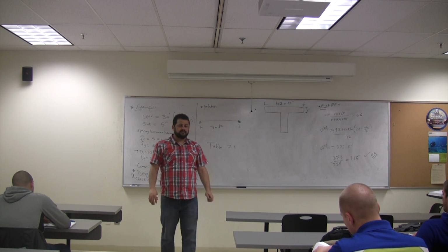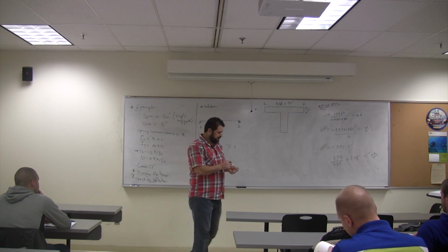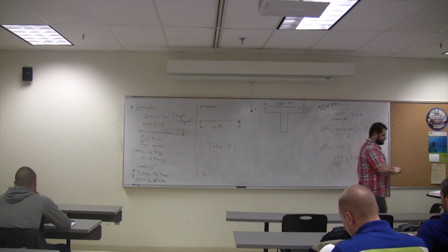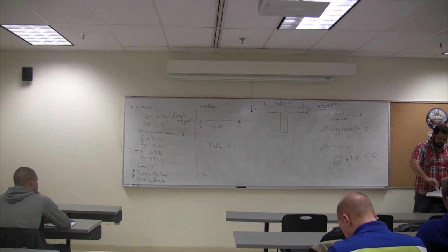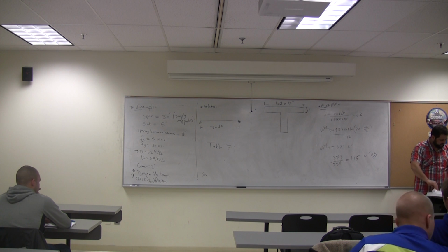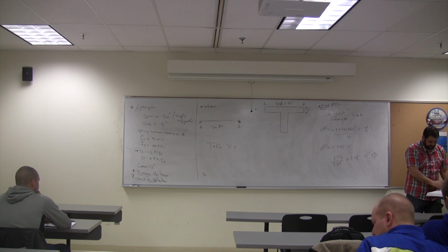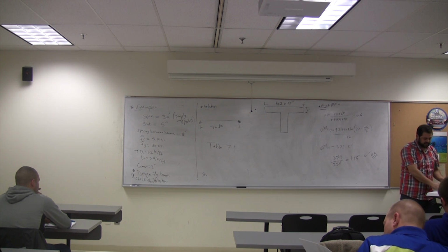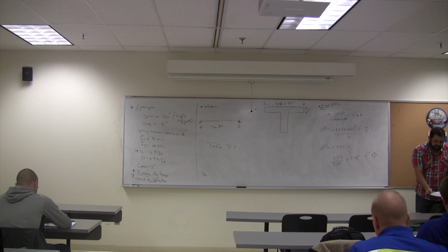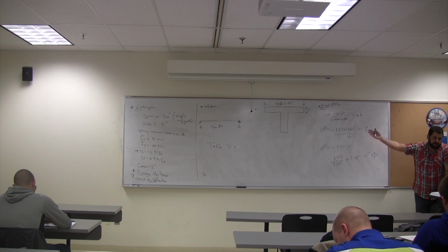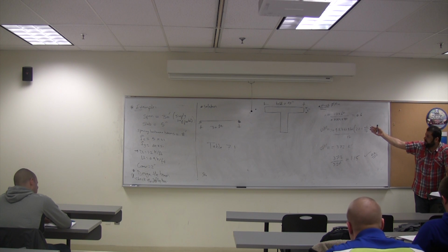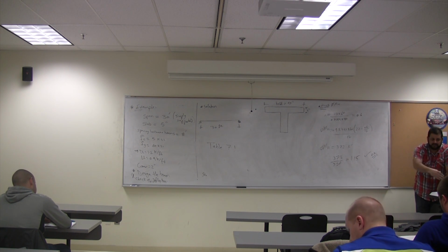Remember that? It's Table 6.1 for us. That table gives limitations for solid one-way slabs or beams or ribbed one-way slabs. Our customer here is a beam, right? So we're in the second one.